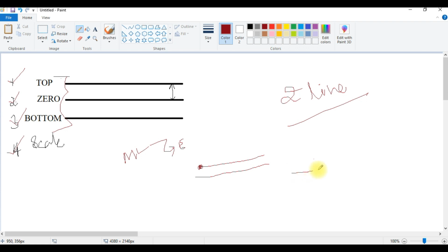So I am considering this as my reference line, indicating OO. When I draw a multi-line, right now you just assume that by default in AutoCAD you get two lines at a time, because of that reason I have taken this one. So consider this as your reference line OO. Why am I taking this OO as a reference line with the help of this brown color? Because when I take this multi-line, to identify which one will be the top line or which one will be the bottom line, for that reason I have considered this as the reference line.